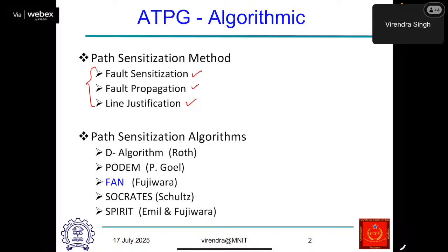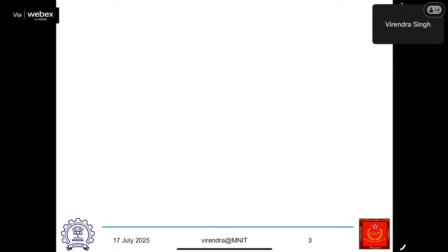So this ATPG algorithm works well if I have a combinational circuit wherein you have some input and then one of the output. Now, when we go for the sequential circuit, in the last class, we discussed that a sequential circuit is basically defined by a tuple, which says that the circuit has a set of states S, and S0 is the initial state. There are input symbols that it can consume. There is the output it produces, and then there are two functions.